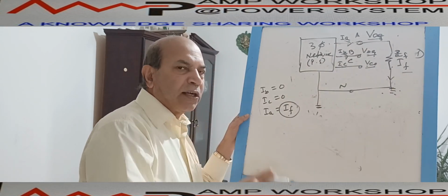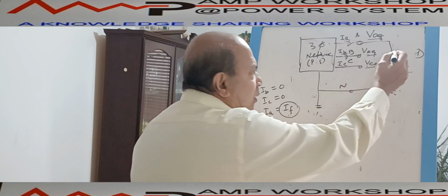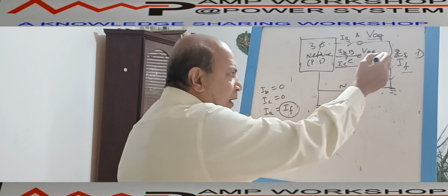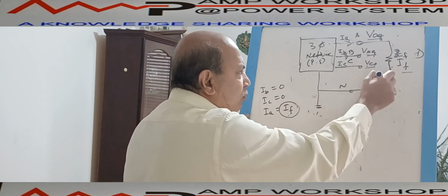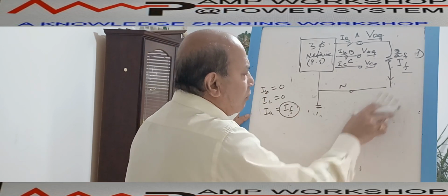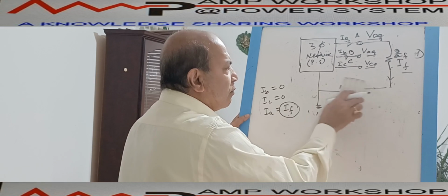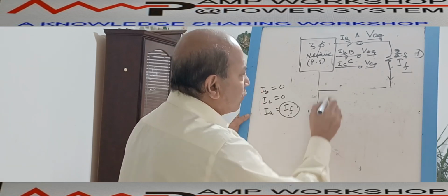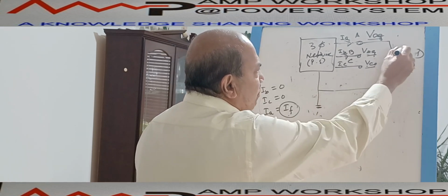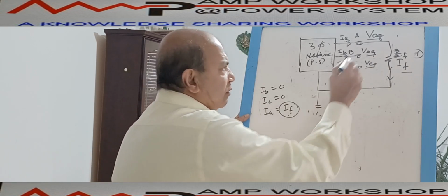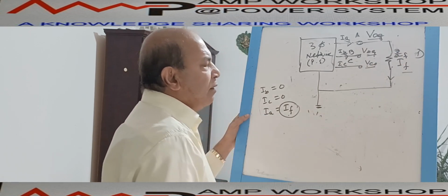So the cable is going to earth through some impedance. That unknown impedance we call ZF. Or when the neutral is connected to the ground, it could be connected through a ZF. Suppose a resistance is intentionally connected to the network, then that could also be considered over here. So the earth impedance, or the impedance in the neutral path, is ZF.